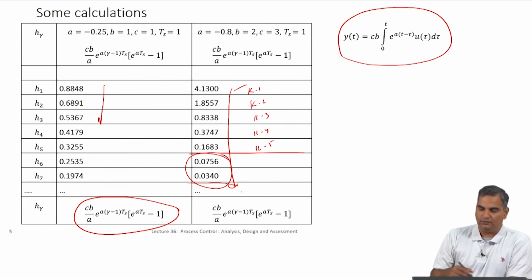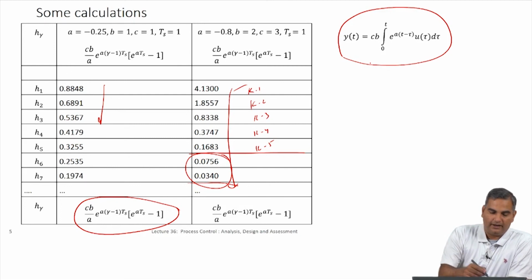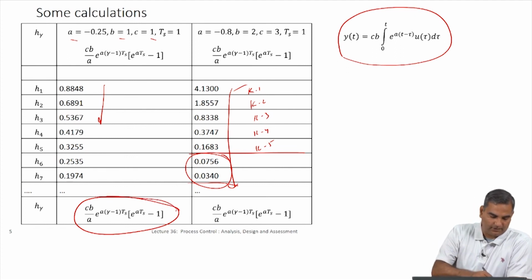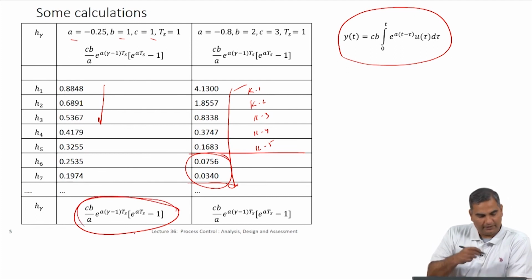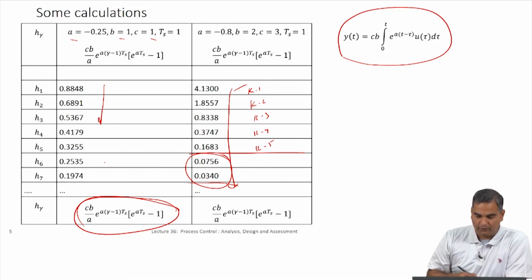But this tells you that for typical systems where we had the state space models and I have taken some values for A, B, C and then actually shown the computations of H, how this formula is derived I have not told you, but I have just told you that if you were to compute this, it will keep going down. At some point the memory effect will kick in and these coefficients will become smaller and smaller, so that adding them in the model does not give you any purchase.